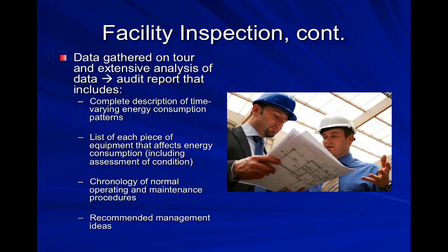So we're going to need this extra information that's here. All the things that are listed on this page. In addition, it's good to know that there's many times pieces of equipment have built-in time meters that are going to measure the amount of time it was in operation or in standby. And these functions are not always utilized, and it might be a simple thing to go into a menu and have that particular monitoring turned on and reporting made available.